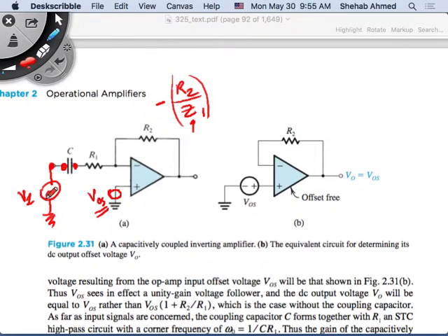VI? This is your sensor. Your sensor wants to pass AC through, actually. It's an AC signal. You want to pass some time varying signal through. You want that to go through, right? So, what is the capacitor going to do if this signal is DC? It will be an open circuit.